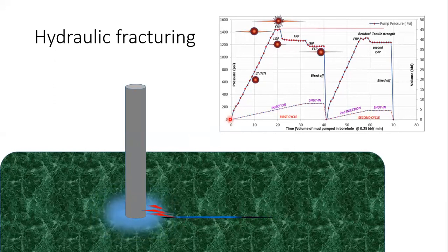From here onwards, the pressure starts from zero and begins to rise. It will go on rising until it creates one particular slope. Up to here, the slope is almost linear. Then after reaching here, it will start to deviate towards the right side. That means this is the point where the fracturing fluid started to enter into the formation, apart from the channels that have already been created earlier. Up to now, it was entering into channels. From this point onwards, it will pressurize the formation space which is around these channels.